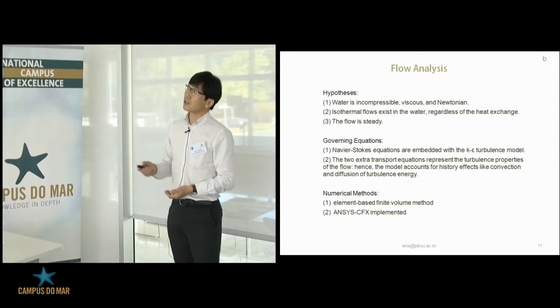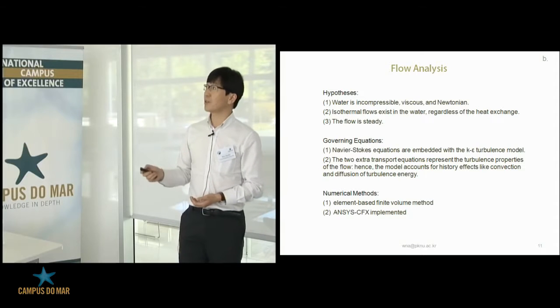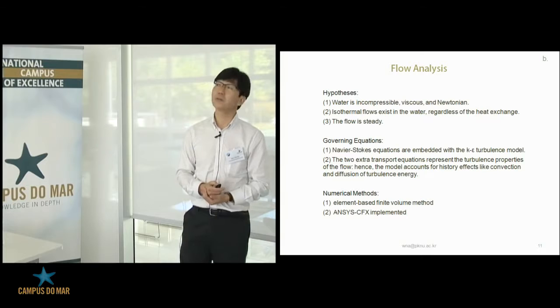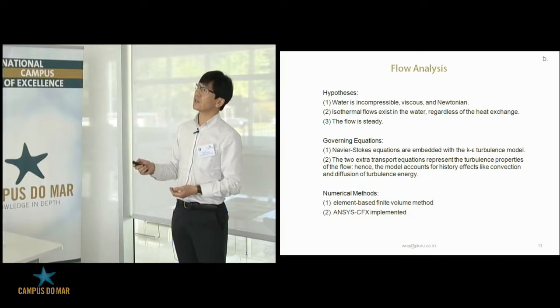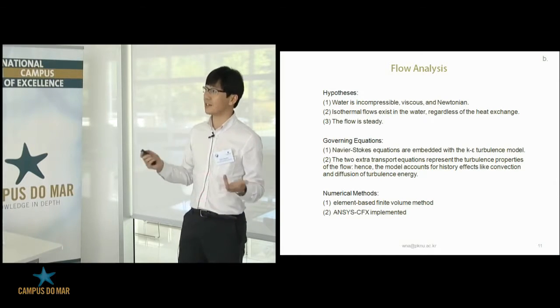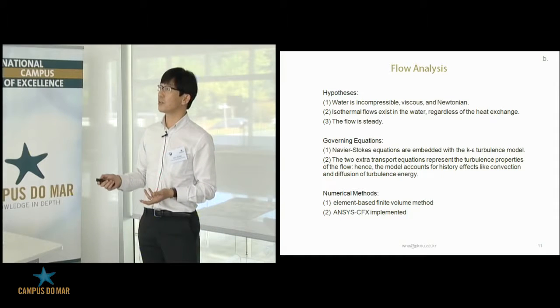For the analysis, I made some hypotheses here. The water is incompressible, viscous, and Newtonian flow. And isothermal flows exist in the water, and then the flow is steady. And the governing equation, of course, is the Navier-Stokes equation, etc. And then for the numerical scheme, we used the element-based finite volume method.